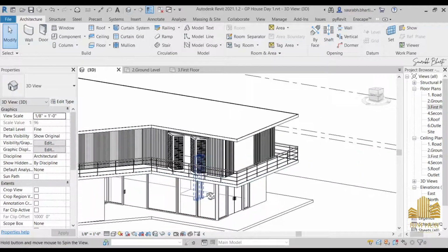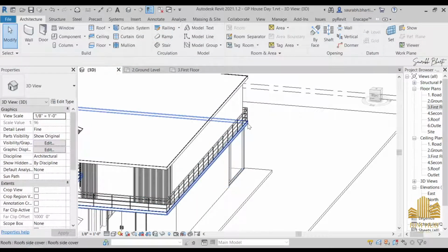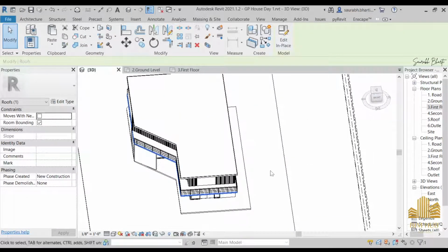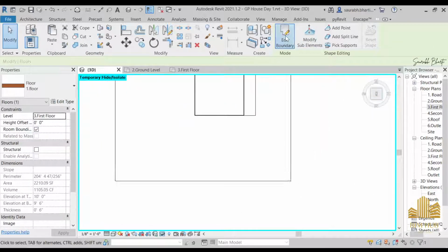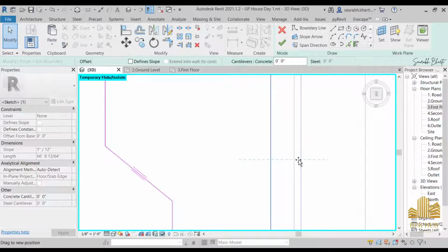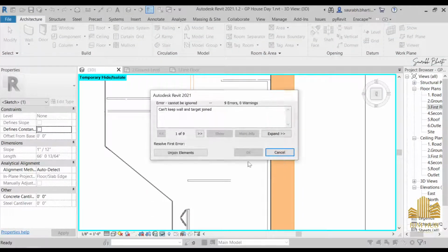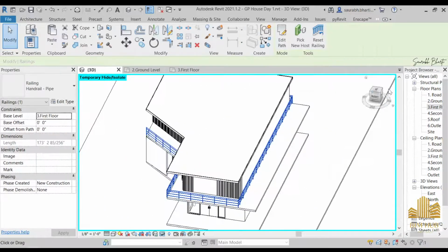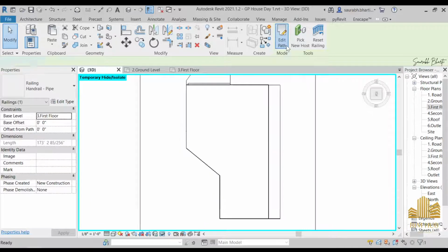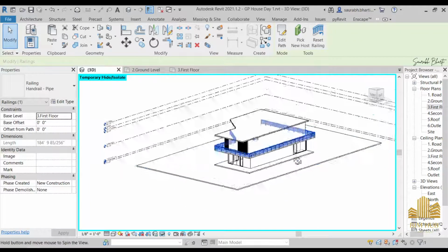If you want to make changes to it, you can also do that, but I have to make changes to this place actually. So just go to, okay, double S to hide this one, the outer layer, and then go to edit type, and we have to increase the size of it till here, and finish. Attach, always remember, and unjoin element, and just go to edit path, and in edit path select this path. Okay, and now we have a railing at this place.